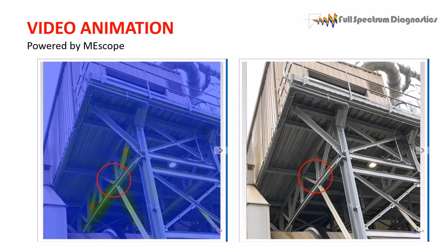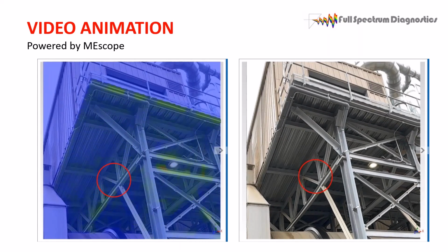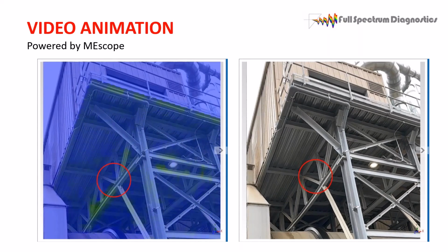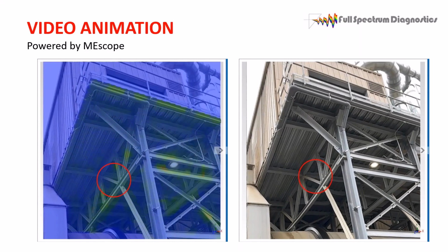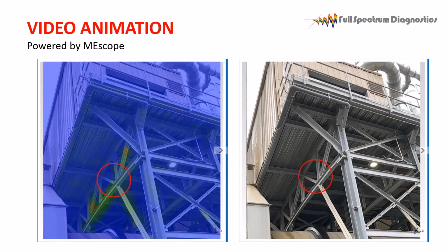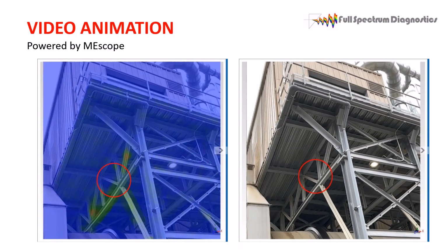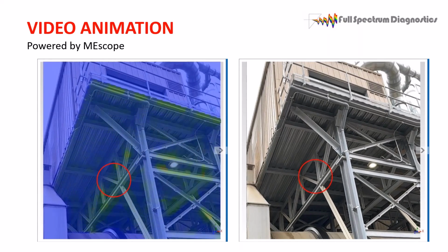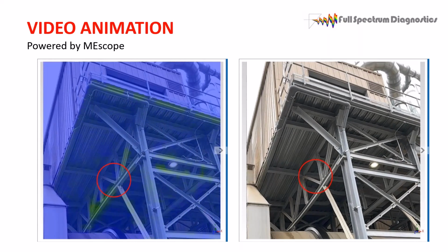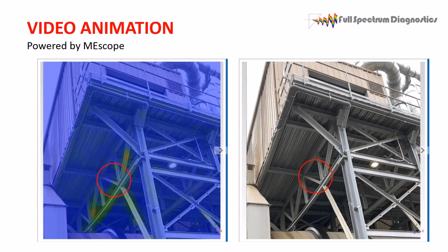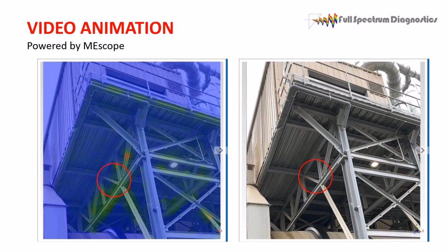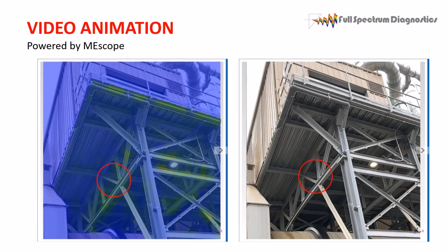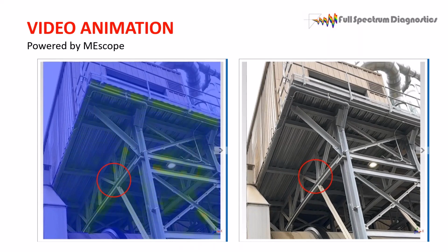This is actually an operating modal analysis. There's a lot of talk about doing this, hitting with a hammer and doing a modal test, but it's too hard. For something like this, you couldn't get up that high. We had to get some painter poles and put them all together and move an accelerometer around for several hours to map the floor out. But that's what we were getting.